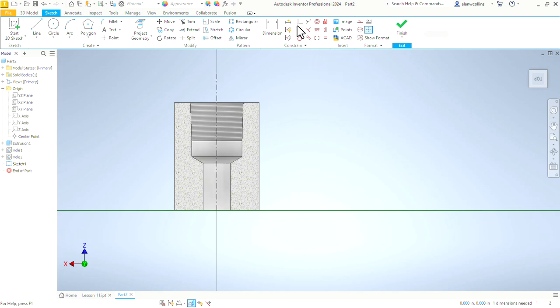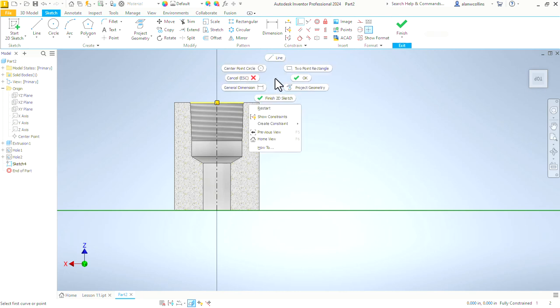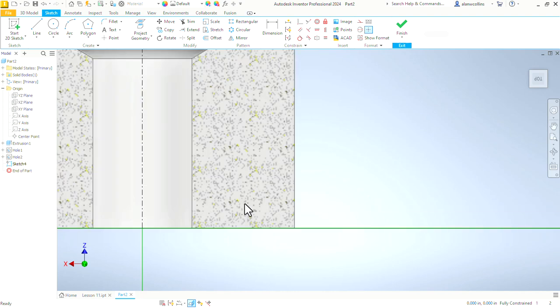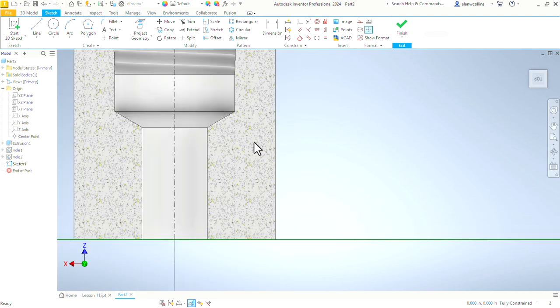And just so that our sketch is fully constrained, let's place a coincident constraint from the endpoint of this line onto the top edge of the part, and that gets it locked into place. We can draw our profile that we're going to cut around either side. Let's work off to the right here, get at a spot where we can kind of see what we're doing.